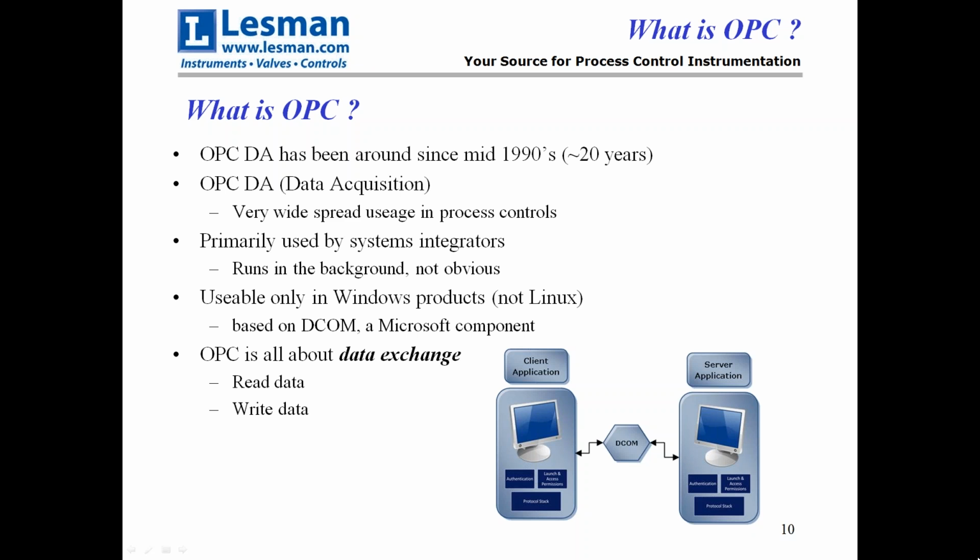Now, one thing, yes? Is OPC kind of like the universal translator between two different systems? Is that one way to look at it? It's a universal translator between an OPC server and an OPC client. So any brand OPC server talks to any brand OPC client. At the very lowest level, you still have to have a driver to get to the final device. But that's actually a good way of describing it. Yes, it's a universal translator between OPC units.